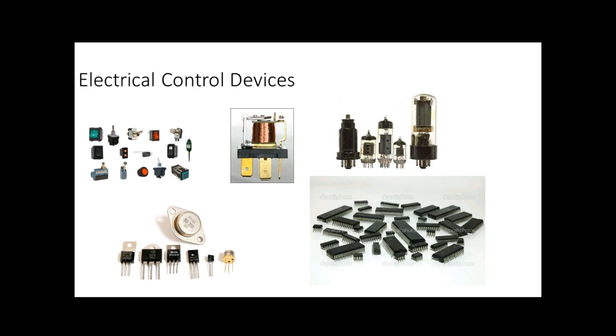So what we do in a vacuum tube is we have an element in there we call the cathode that we heat up, and it's made out of material that when you heat it up, it releases a cloud of electrons. And then we have another element in there we call a plate, and it has a positive charge. Now what are those electrons over here going to do when they see this big positive over here? They're going to go flying through that vacuum over to that plate, right?